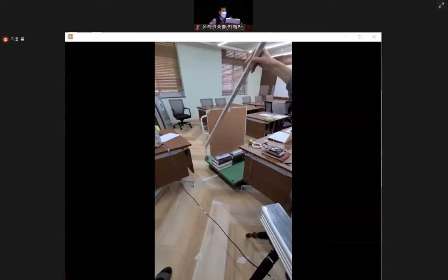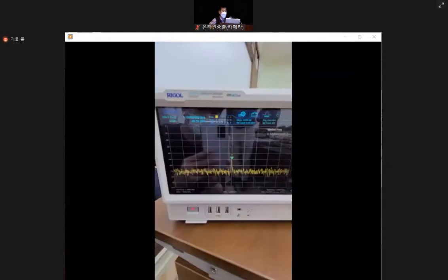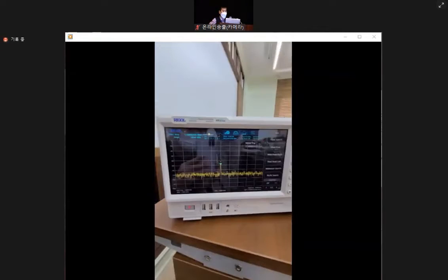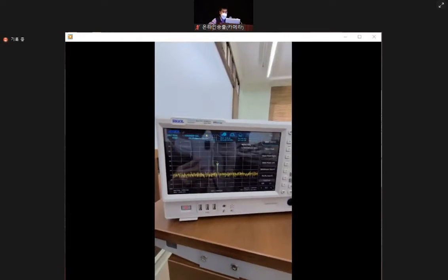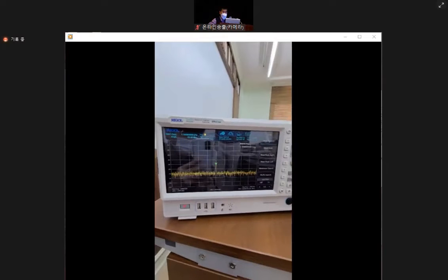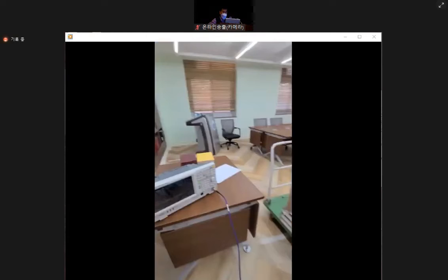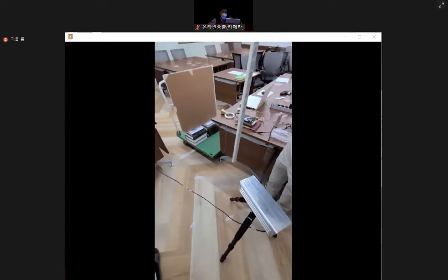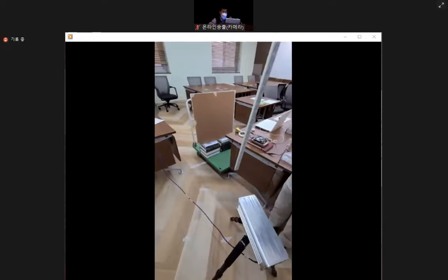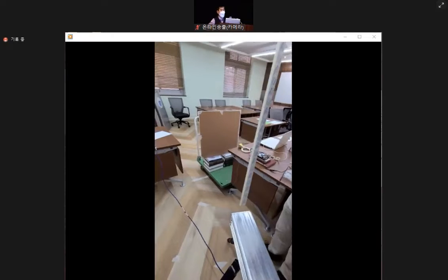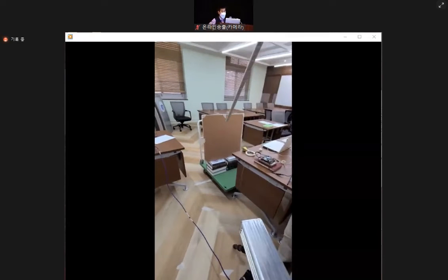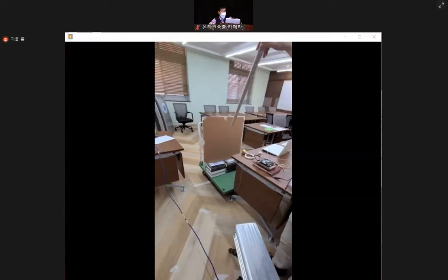Let me check. Let us check. Yeah. That reads around minus 50 point something dBm. So you can see obviously the difference between the signal strength at the 41 degrees and the signal strength at the 20 degrees. So the noise has been removed. Why? We could do that by moving it further away from the surface of the material.